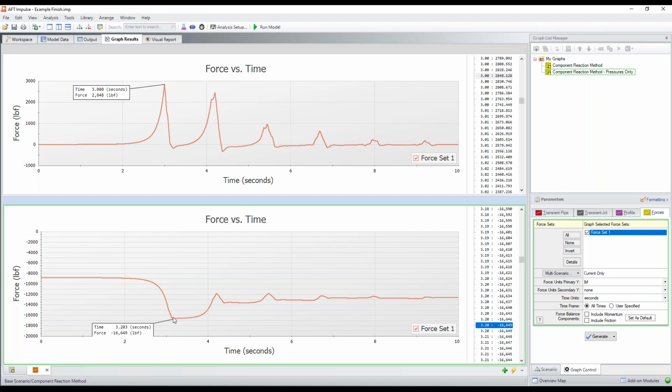So you could completely either over-design your supports or just design them in the wrong primary direction, I would say, if you use this more simplified method. And I would say further that this more simplified method presented at the bottom here actually includes more pressure forces than just the endpoint pressure forces. So if you resort to the endpoint pressure method, your results will be even worse than this. So don't rely on this. It can very easily be dramatically different than the true values. So that is the beauty of computer simulation, is we can get that very easily.